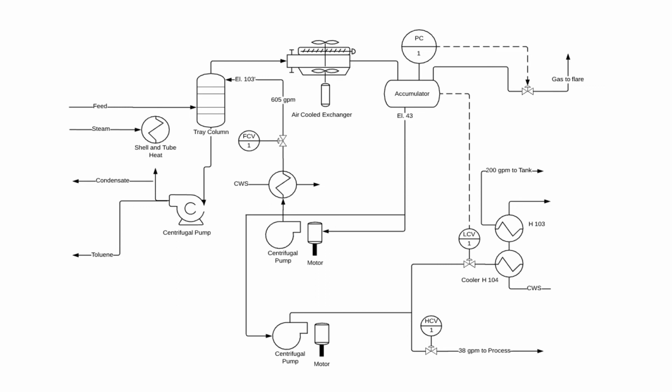Sometimes you see these arrows, they're either coming from off the page or directed off the page. So these usually have a tidbit that tells you what P&ID it's coming from or going to. This allows you to trace lines further through the process, because usually you can only fit a couple pieces of equipment on one P&ID. So if you need to trace something further, you can follow it to the next P&ID and so forth.